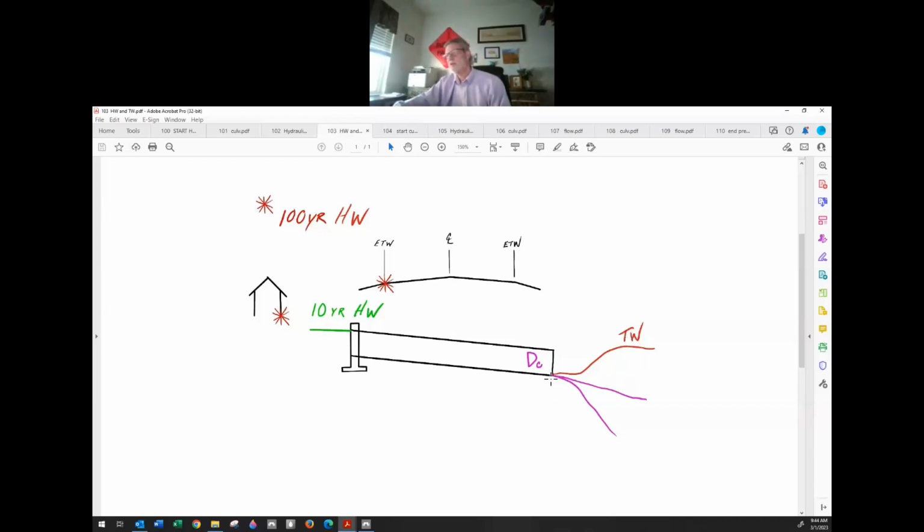And now looking at the other end of the pipe, we have to consider the tailwater elevation. So if it's like this purple one here where it just falls right out and it doesn't create any kind of a backwater condition, then the tailwater elevation will basically be 0. And then we're going to end up using the critical depth from our calculations. And then we'll take the existing flow line elevation right here and add the critical depth to it to get the elevation for the tailwater.